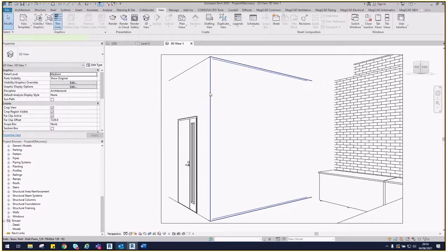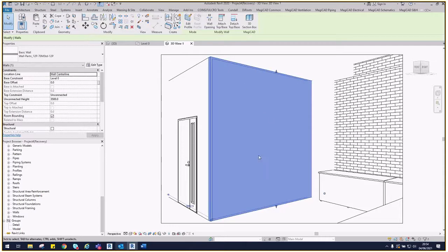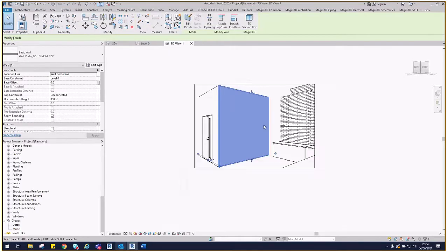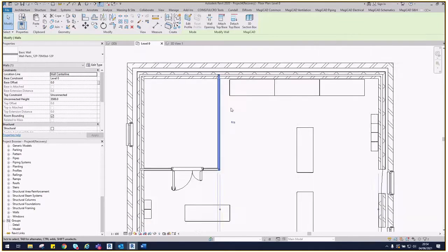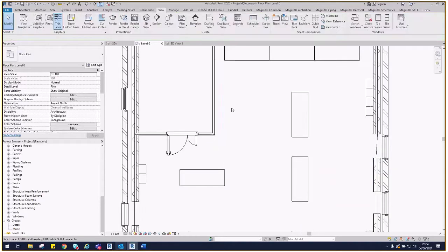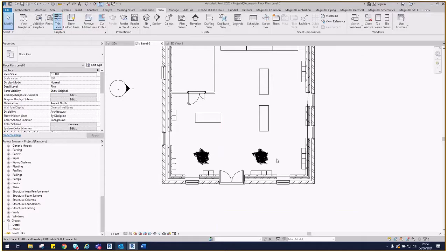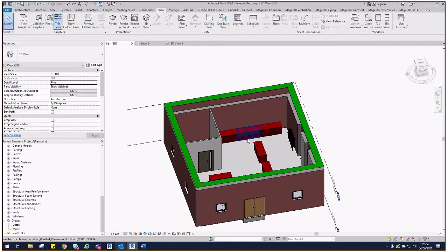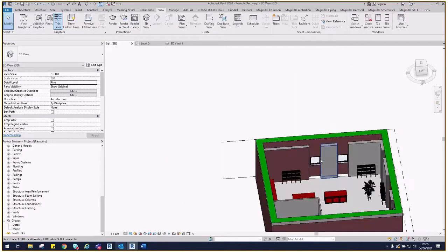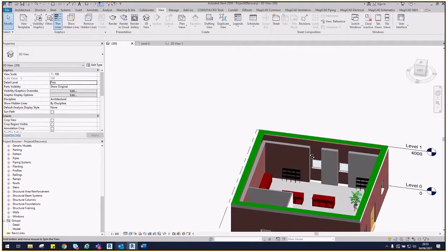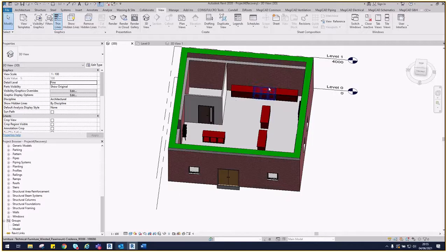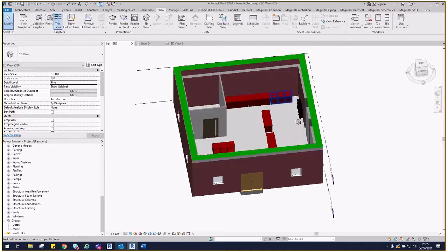However, because we haven't set any of the architectural parameters such as wall colors, most of the renders on this won't be working. So a process that we have to go through before we do any of the renders is to go through and select all these materials and select the final finishes. That can take quite a lot of time. Most of the items, such as the trees, will already have the finishes in, and as we can see those in the 3D view, they are already green. However, all of these other items are just in brick or standard grey materials, which shows that there is actually no colour associated. Although if we did try to render, the cabinets would turn out to be red, which obviously we know wouldn't be a typical colour.